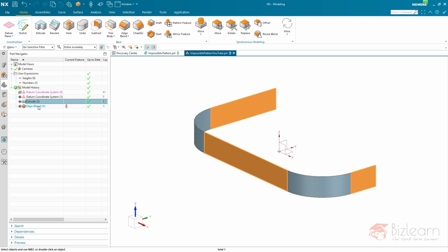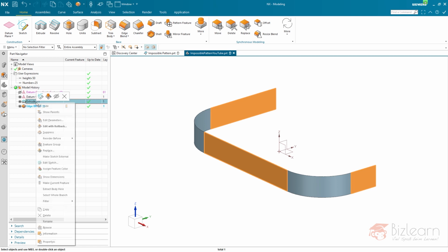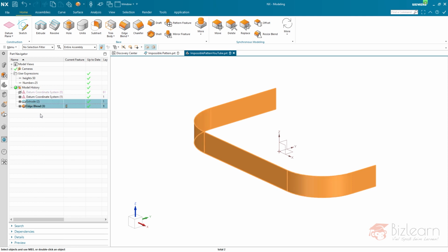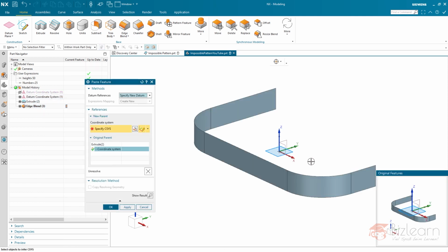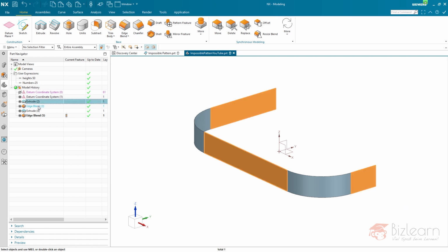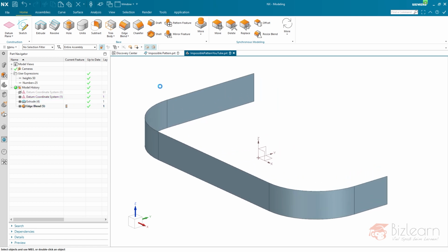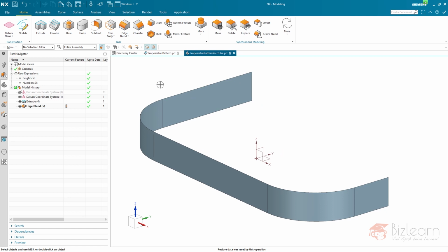Well, how can I repair this? There are a couple of opportunities now. You can repair it within the sketch, or what you can do instead is just to copy and paste this on the display coordinate system like that. And now I'm going to delete the old features. Now you can see we have a relation to the second coordinate system, which is better than having a relation to this one. I am also producing mistakes. I'm not going to cut it from this video because it's somehow a good reminder for you.